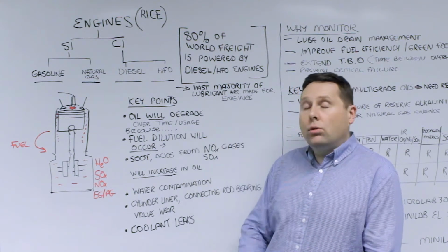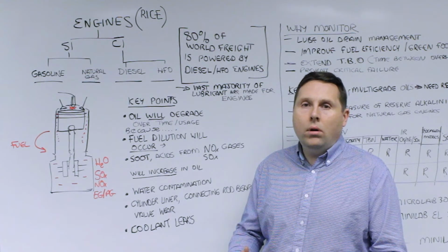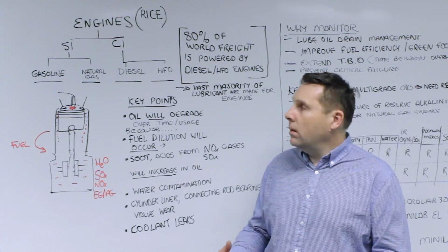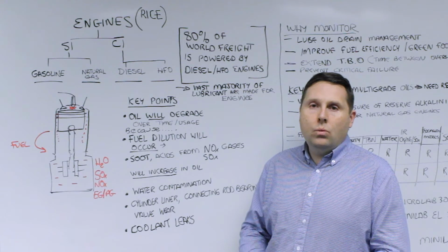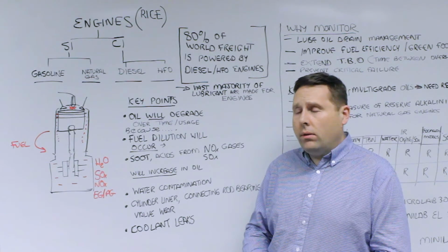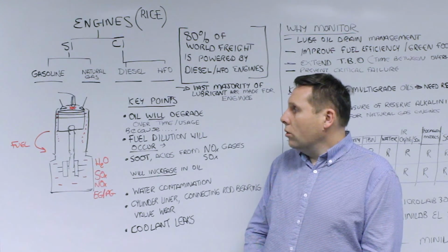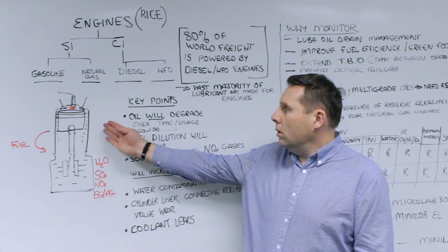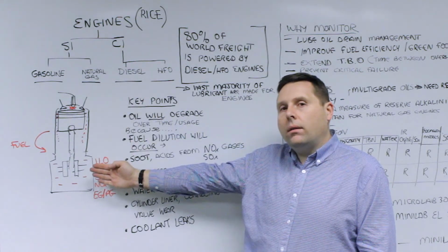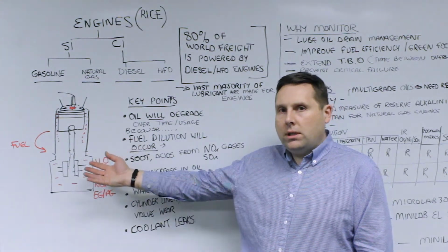The vast majority of lubricants that are actually manufactured for the marketplace are either passenger car motor oils or diesel engine oils, and so they lead in terms of formulation development, and there are still millions of engines in operation worldwide performing critical functions. What do we care about in engine applications? Well, what's interesting about an engine is because of its compression cycle, you're always going to get some of the fuel that you are burning somehow getting into that crankcase, and so over time that's going to degrade the oil and then potentially damage the engine.